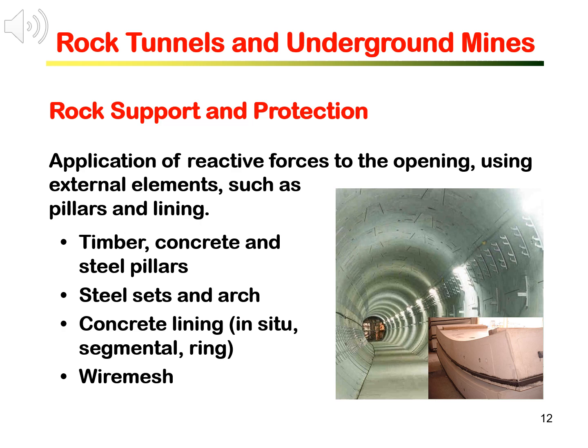The common structures for rock supporting in tunnels and mines are pillars and lining, using concrete, steel, and timber, such as steel sets, steel wire mesh, and concrete lining. Prefabricated segmental concrete lining is a standard supporting structure for tunnels excavated by shield tunnel boring machine, as shown by the photo on the right.